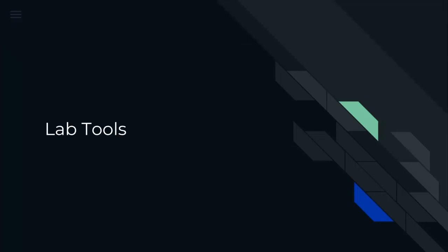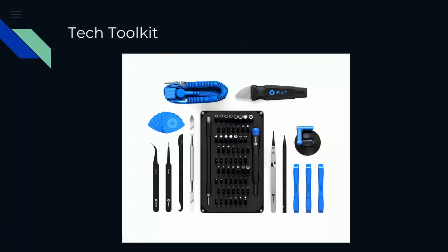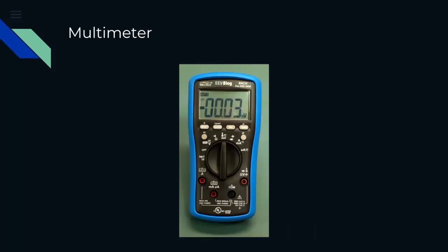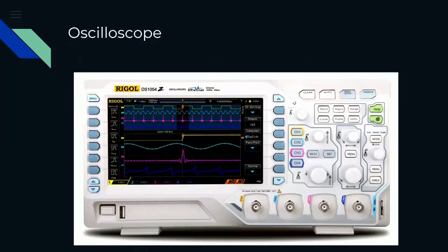Okay, so lab tools. That's kind of silly, but we have to open the device, we have to sometimes disassemble the device, so screwdriver set, reflow and multimeter orchestration. Sometimes you have to remove a chip from the device itself. Multimeter, we have to check the connection. Oscilloscope, sometimes you have to sample a signal very fast so you can see how the signal goes and understand in minimum time what's happening on the device.